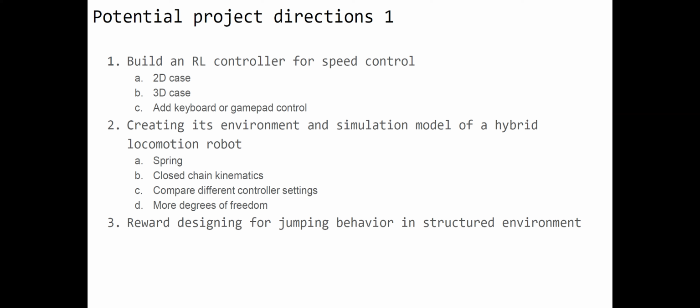If you know what closed chain kinematics is, good, I will not explain it here elaborately. But you can work with this. The main key thing in MuJoCo is that it can work with closed chain kinematics, because for standard URDF models you can work only with open chain kinematics, but MuJoCo plays with XML formats, which makes you able to make a cell with equation. You can read the MuJoCo documentation, and you can make closed chain kinematics.